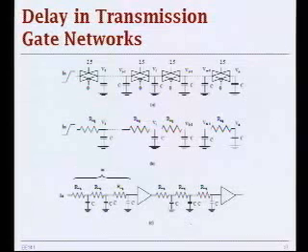How do I solve for the delay of this type of RC network? Ooh, silence. How do we solve that delay? You can use Elmore. And what does Elmore say? What's the delay through this path, the one in the middle?